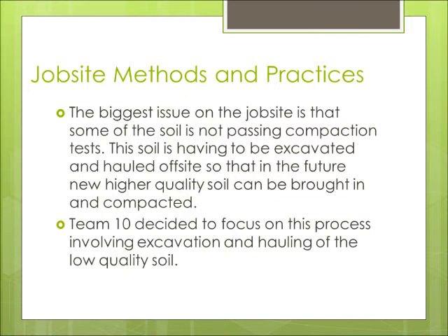During Team 10's initial visit to the job site, there was one big issue that Price Construction was facing. This issue was that some of the soil was not passing compaction tests. Price Construction decided they needed to excavate and haul the soil off-site so that in the future they could bring in higher quality soil so that it could be compacted and pass the compaction tests. Team 10 decided to focus on this process involving excavation and hauling of the low quality soil to model and optimize.